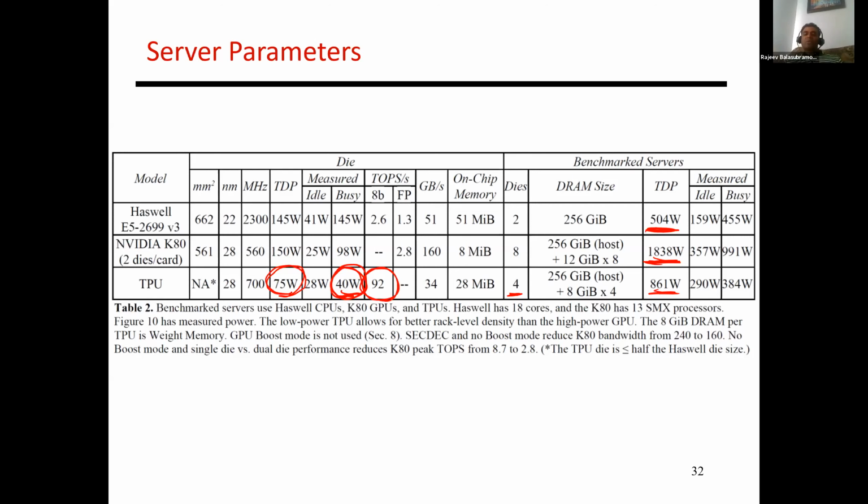So there's a question about whether there are dynamic things like frequency scaling, DVFS, and on-off mechanisms. I'm not aware of this being part of the TPU. In fact, the TPU paper makes a point of saying that they didn't have time to do all this, right? They did not even have good clock gating mechanisms. I'm not sure if version 2 and version 3 have more of this. They did put it on their roadmap of things their engineering team would eventually get to, but it's not clear if that's actually a part of the TPU.